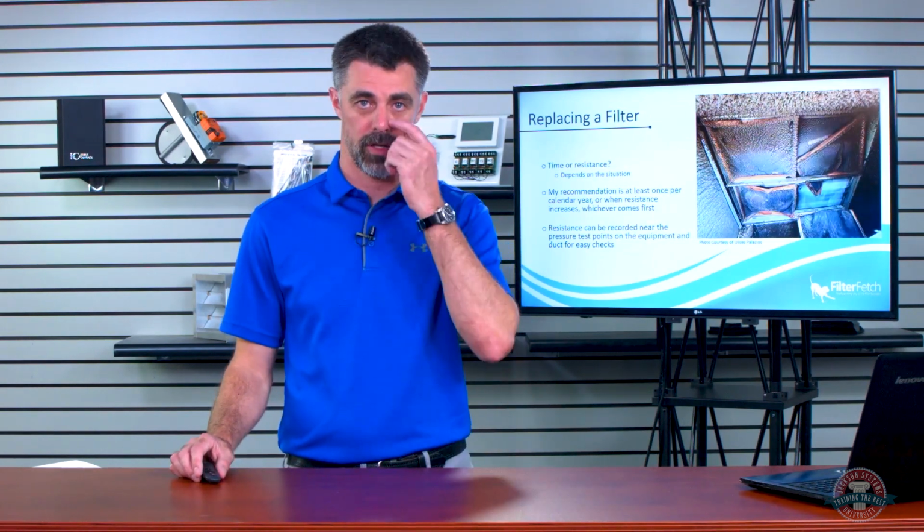If you look at the watts of the motor at one resistance versus the watts of the motor at another resistance, you can kind of figure that out. But how often is that motor going to run at those watts? Especially if you're talking about an ECM, where they will change constantly during the runtime. So it becomes really challenging to talk about energy savings with regards to filters.